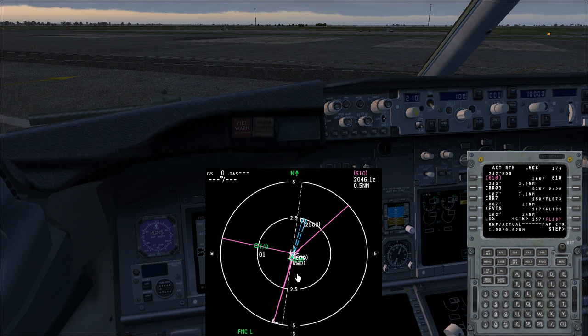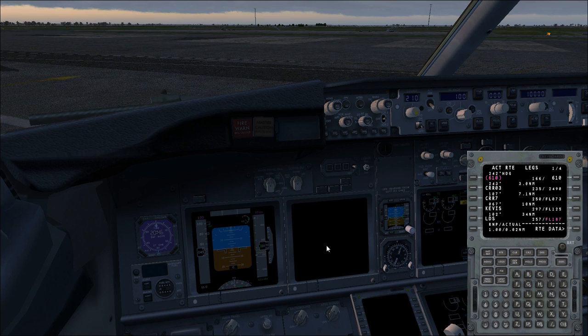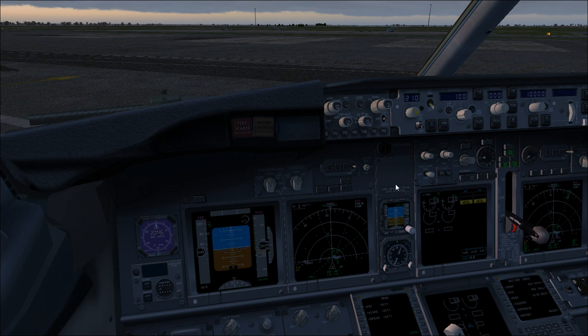We have all the information given by the route, all the arrival runways with their center lines. We have all the procedures displayed. I have selected, actually if you are giving arrival, this is not so important. The thing I want to show you is that the channel line is the actual missed approach route. The missed approach route will be not armed and not active until you press takeoff go-around, and after you do the go around or over the runway, this blue line will be magenta, and the missed approach route will be active.